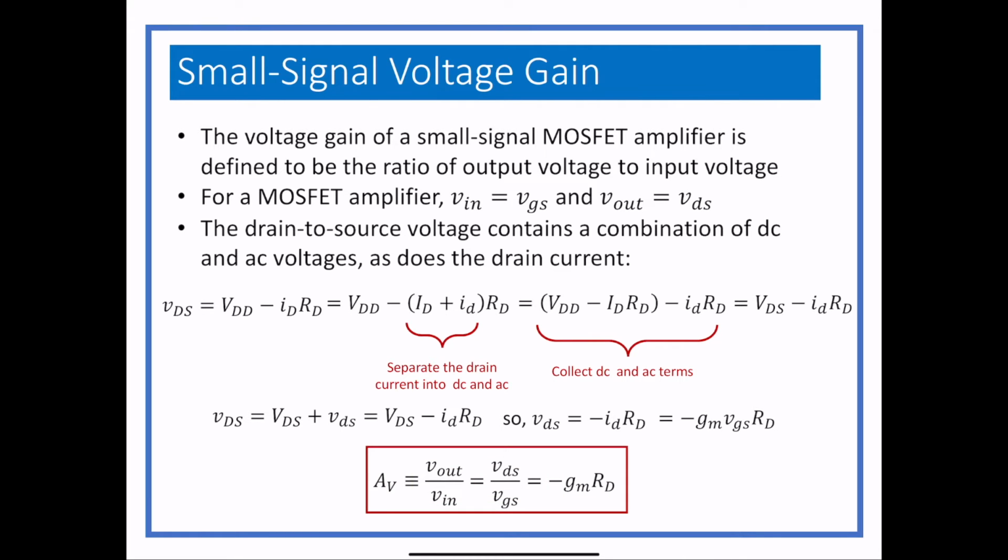The gain, and remember there were three types of voltage gains from way back when. One was Avo, which was just the amplifier. Yeah, I know, sure. You remember, don't remember. I'm going to explain it again next time also. I will tell you the difference. Av is supposed to be the voltage gain without a load resistor, basically. Actually, Avo is usually the voltage gain without a load resistor, but again, it won't matter because you'll just need to find the voltage gain for the whole circuit, and that won't make any difference. So it'll be okay.